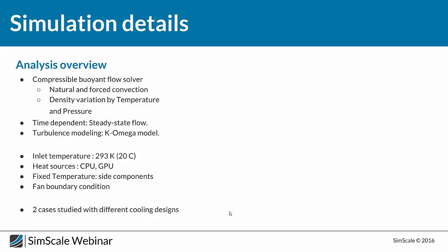So in general, there are two types. One is called the transient analysis and the other one is steady state. In the transient analysis, we also have the marching direction to be time. So the solution is being calculated in the direction of time as well as along the domain, and we could see the temperature in the domain at each and every time instant. But in a steady state analysis, it shows the result at an infinite time. So after all the heat transfer taking place and the steady state has been attained, we see the steady state result.